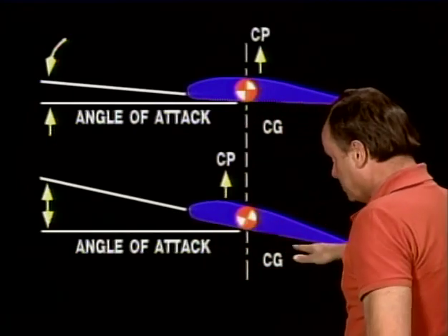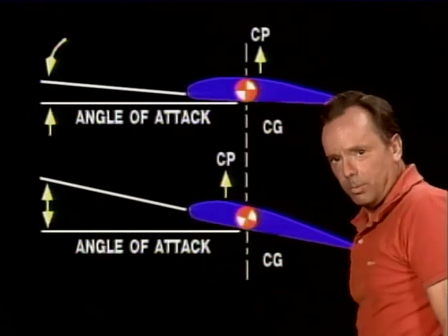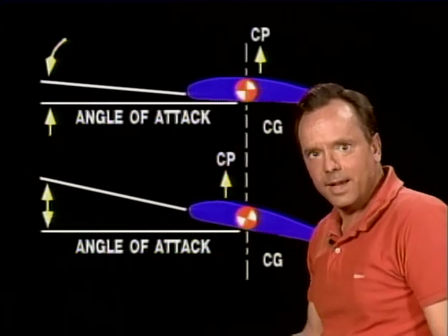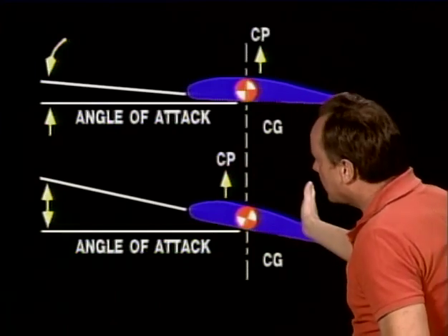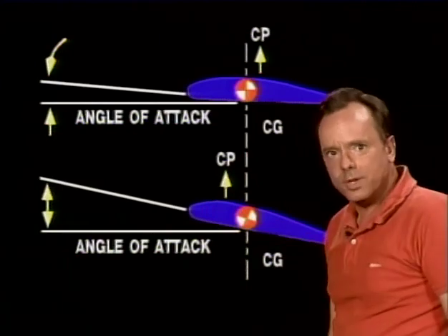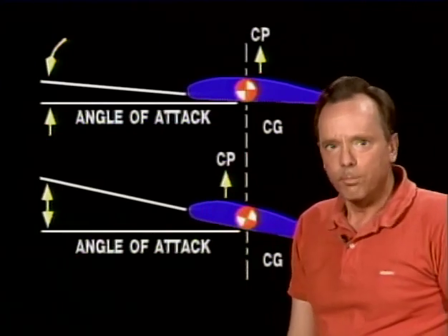Now, that's a non-symmetrical wing that happens to them. Most wings are non-symmetrical, so you can leave that out. But as you increase the angle of attack, the center of pressure, which you can think of as being the center of lift, moves forward.